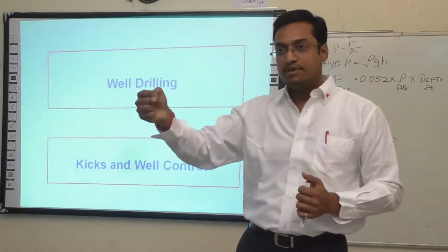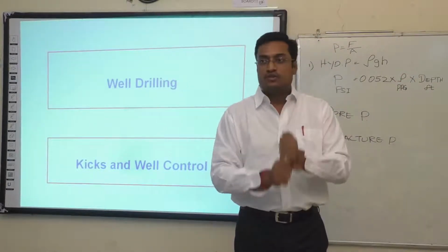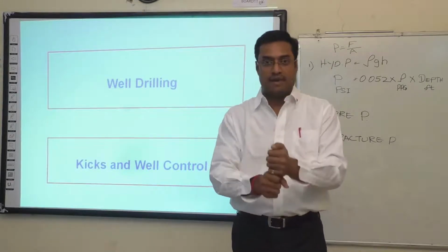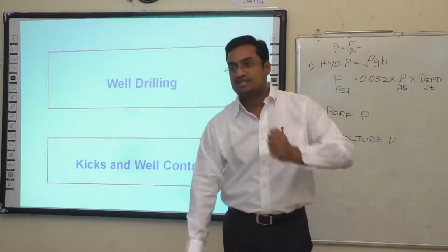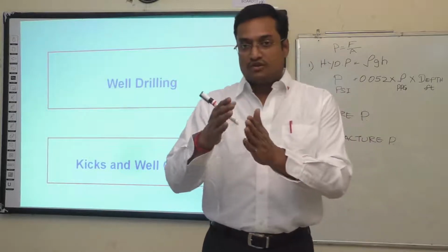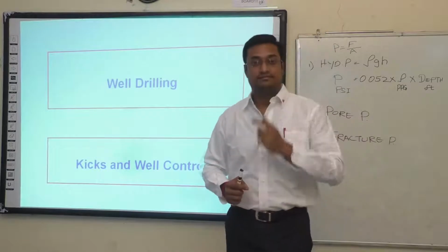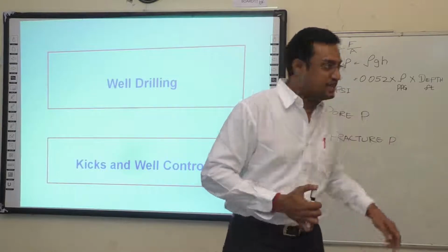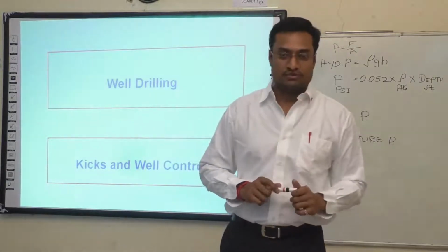It may be because of the pipe which is getting stuck, or because of shales which are swelling, which will make you stop, or you will not be able to pull or push the pipe, or if the drill pipe or the drill string breaks and falls inside the wellbore, that becomes a drilling equipment problem. So here we talk about well control problems and the control methods. So any problem which is caused inside the wellbore because of the pressure differences between the hydrostatic pressure and the pore pressure is called a well control problem.